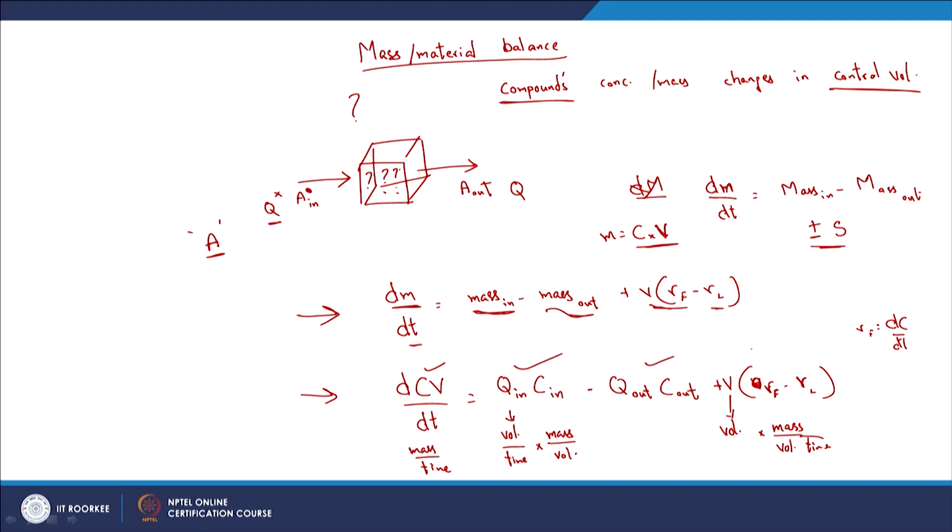So for all the 4 or 5 sets of variables, we see that the units are mass per time, in the way that we have written this equation, right. But one aspect, as I mentioned, is that we wrote down the equation for macroscopic systems. In that sense, what I typically mean is the control volume that I have here. When can we apply this particular equation? When the concentration of the compound inside the relevant volume is the same throughout the volume or the reactor, right. But obviously when you have microscopic systems, you have concentration changing with distance.